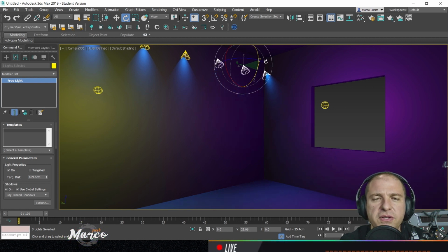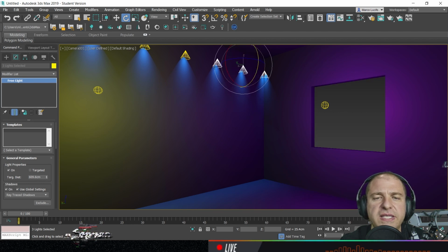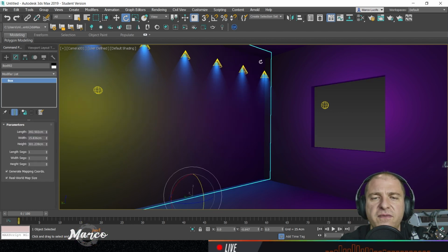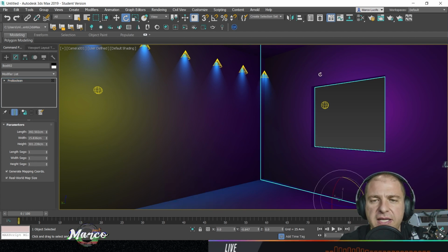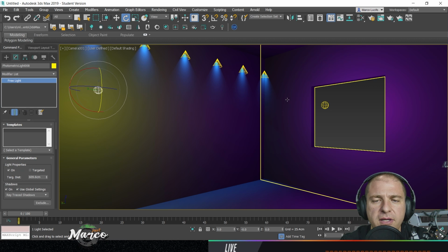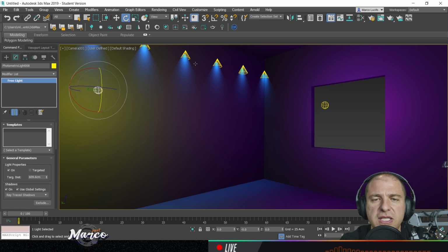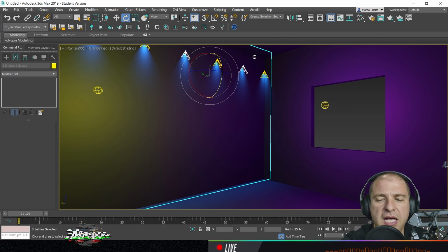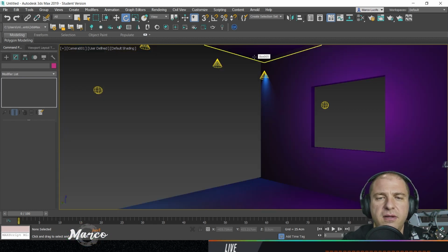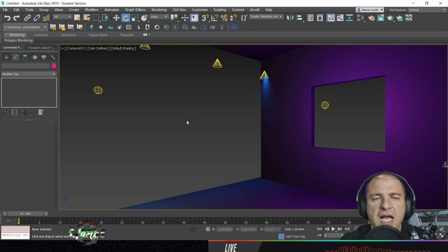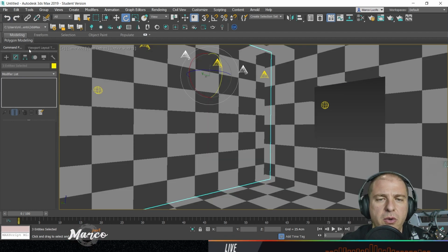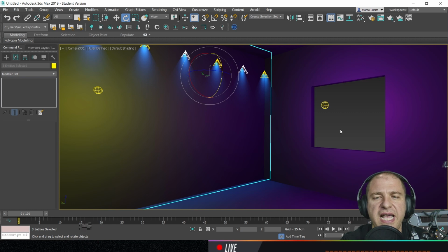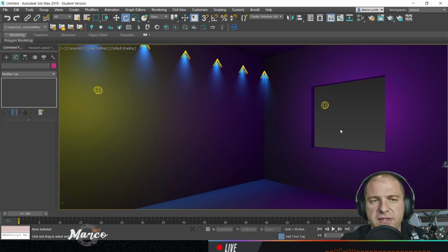It is pretty common instead that when we select this light by mistake, for example, we can select unwanted elements, like the wall in here, the wall in there, and let's say I want to just delete these lights. By mistake, I've selected the wall. I hit delete, and I have to, in general, go back, undo, deselect everything, and this is pretty annoying.